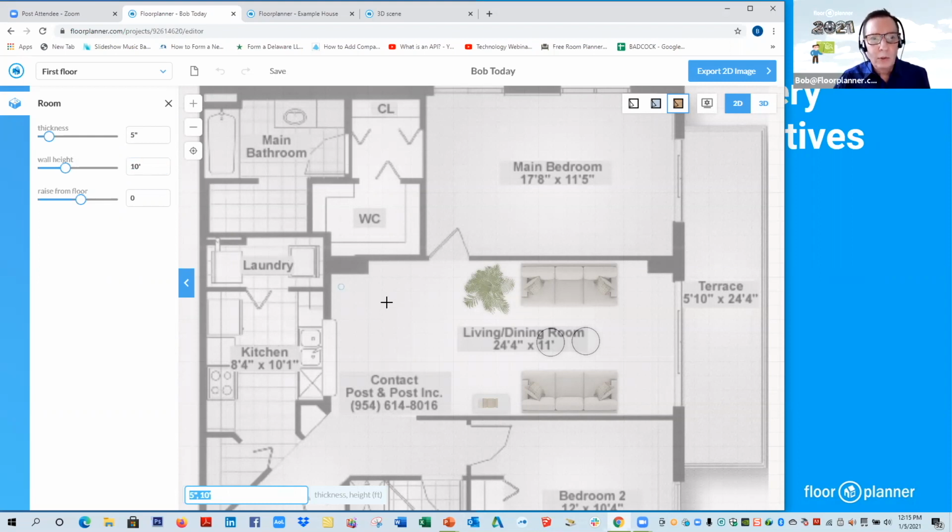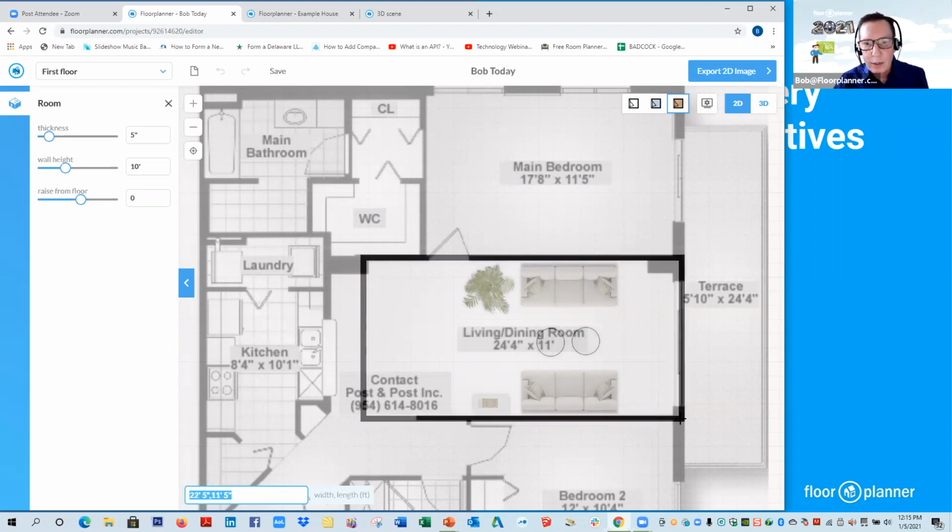With all these dimensions in there, your crosshair over here represents the middle of the wall, not the edge, although we're going to be lining up with the edge of the wall, but that's the middle where it's going to draft. The blue circle inside the crosshair is the diameter of the thickness of the wall we just identified, 5 inches. You want to draft from the middle of the wall, not the edge of the wall, and the middle of the wall in the other direction. So I'm going to find the corner in the middle, left click, and don't let go. Drag out anywhere from that one point. I haven't let go of my mouse click, and I'm visually trying to trace the inside edge of the image I can see behind it, which I know is the right real world scale. Trace it as best you can, let go.